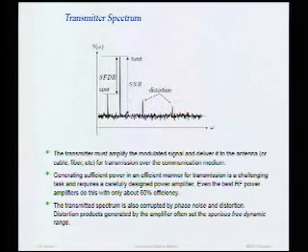That's not too bad, big deal. Build a little low-pass filter, you get rid of that. Well, as we'll learn in this class, distortion is not only generated at harmonic frequencies, but intermodulation and cross-modulation distortions are also created at our own frequency. So if the PA is very nonlinear, it will generate distortion in band, which will actually corrupt the signal that you're transmitting. And we'll learn how that happens later on in the course.